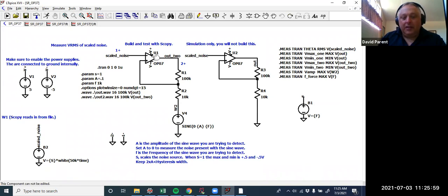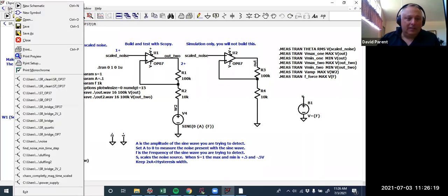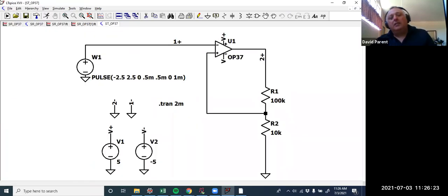Now, things to study: does the brand, or the style, of op amp affect it, right? What about the gain bandwidth? How about the open loop gain? What about the slew rate and all these other things? Even if I'm buying the same op amp, does it make a difference from run to run? And then there's something called the hysteresis, okay?